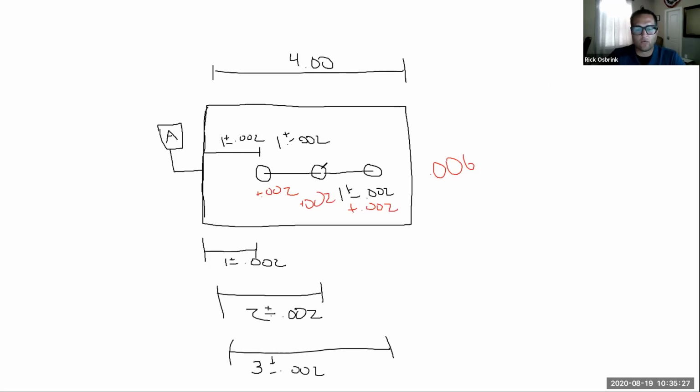And that's why we only use a datum, because over here, if we were to use the distance between this edge and the hole, and then use this datum from this edge to the hole, we can have some tolerance issues between here, because maybe our overall block ended up being 0.002 over as well on this edge right here. So it ends up screwing up our measurements between these holes. So datums are super, super important. So let's go back to our PowerPoint here.